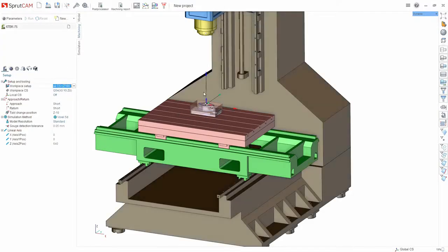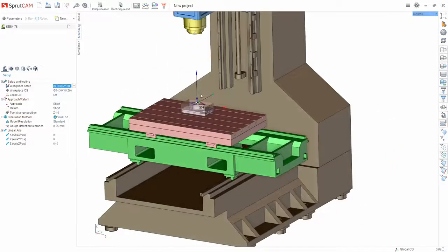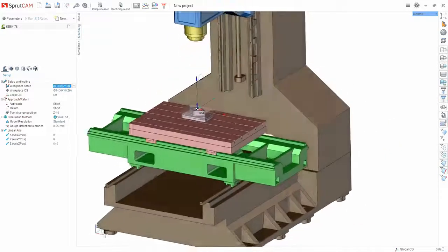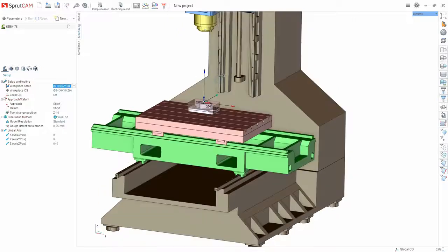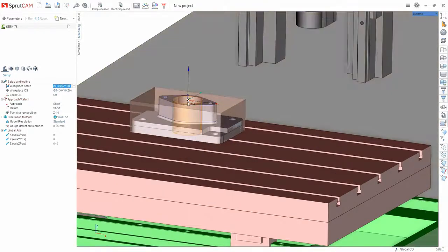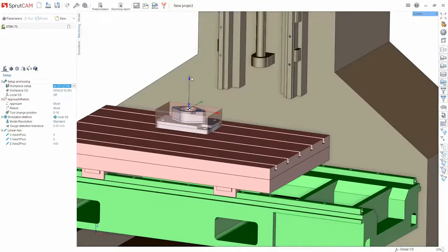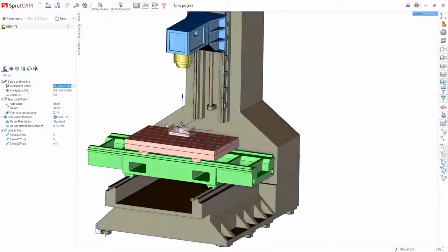Click OK. Now we have moved the part and the workpiece to the top of the table. OK. What should we do next? We already have a part. There is a workpiece which is set by default by the system. There is G54. That is, the binding is also set by default. By default, it's the same as the designed coordinate system. And now we can create an operation.